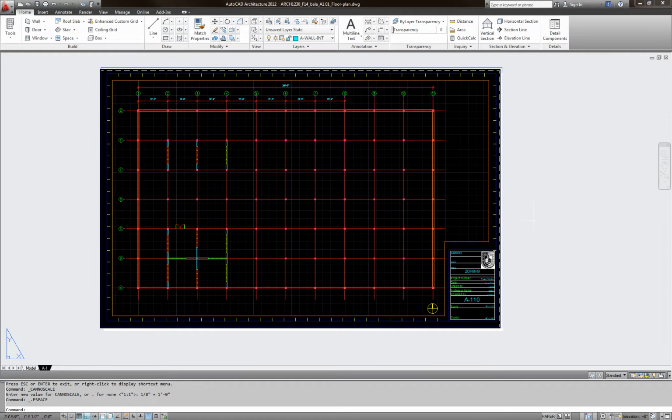So okay, now we are ready to print guys. Make sure you change your name, dates and everything. But before you even print, you have to do two things. One is to type in LTS, line type scale, enter. See right now mine's 96. Be careful, it's not supposed to be 96, it's supposed to be 1. Okay guys, see that now you can see the dash line. If your professor says I don't know what happened to your dash line, this is what happened, LTS.